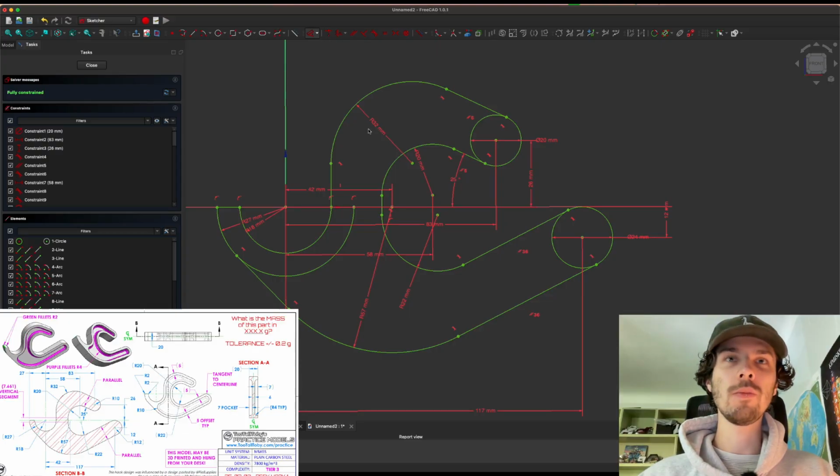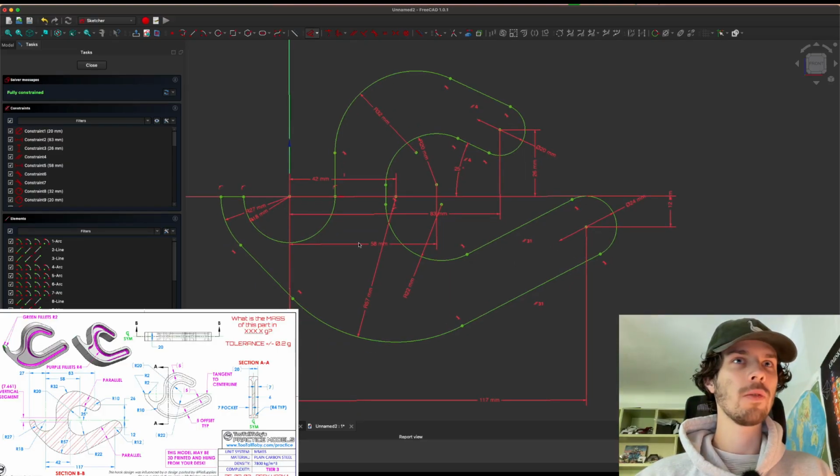Can we leave? No, we actually have to remove the excess material, excess lines with the trim edge. So starting from top, remove that piece, and we have this half circle and another half circle, and we have the main shape ready.